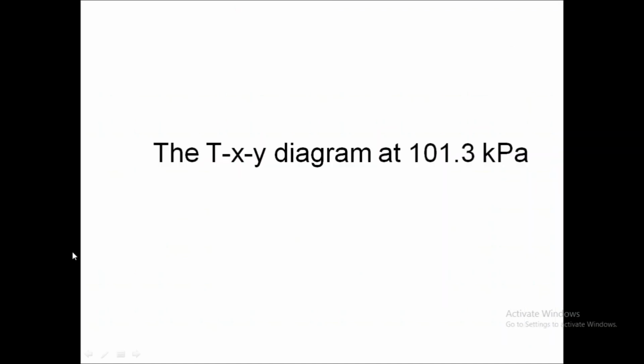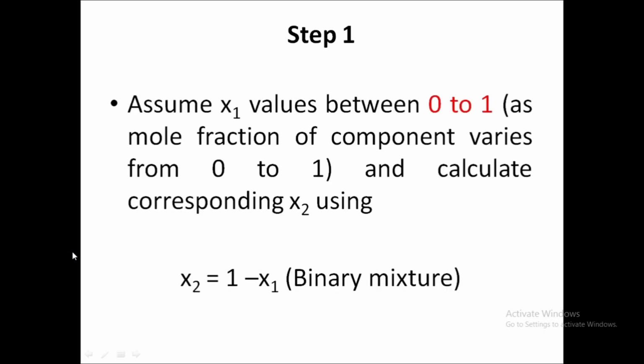The second question, let us construct the TXY diagram at 101.3 kilopascal. In order to construct the TXY diagram, step number 1, assume x1 values between 0 and 1 as the mole fraction of the component varies from 0 to 1, and calculate the corresponding x2 using x2 equal to 1 minus x1, since the given mixture is a binary mixture.